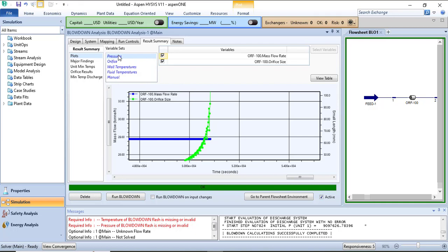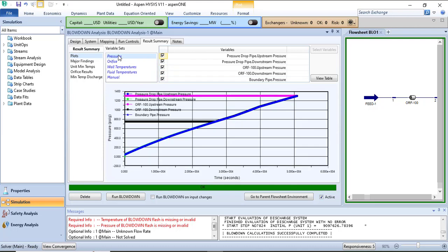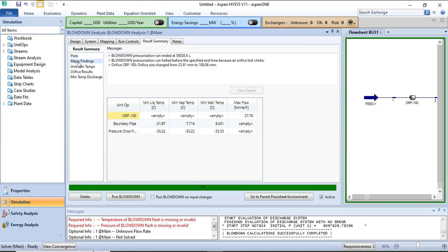So we can also manually calculate the pressure of the control valve. We first see the pressures P1 and P2, then using a simple CV formula we get the CV, and we can check the manufacturer's flow catalog to see where that CV goes, and mostly it will be around 4 to 6 inches. So that's the thing for the pipeline pressurization, and you can see that we had put around 15 hours, but it's completed way before it.